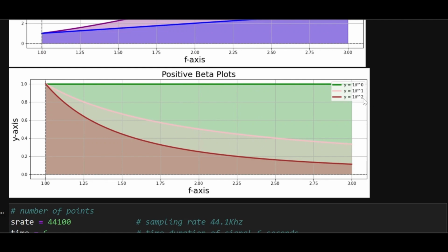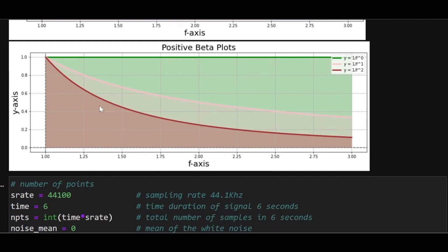And now when we raise this power of beta to 2, it is basically saying that the power spectral density is now proportional to 1 divided by f raised to the power 2. Essentially, the slope has become steeper. It is 6 dB per decade. And this is what is called Brownian motion, or Brownian noise, or Brown noise, which is very important to study from every perspective, including velocity of molecules in a gas, to how electrons behave inside the semiconductors, etc. It's also called random walk.